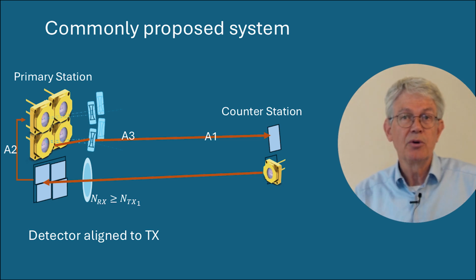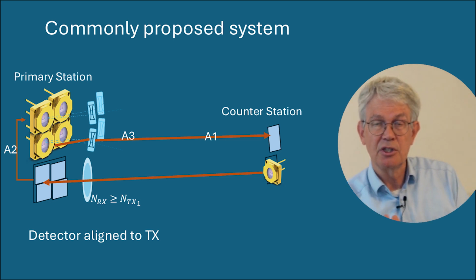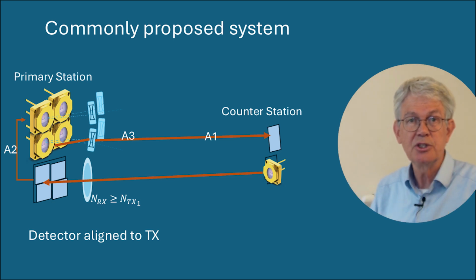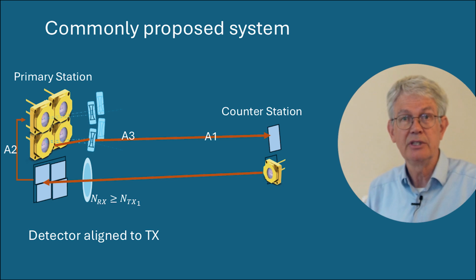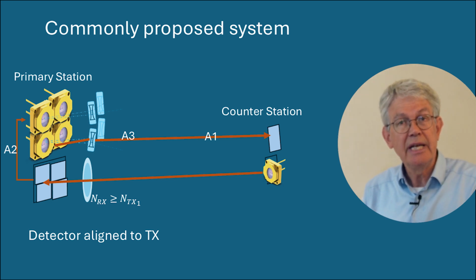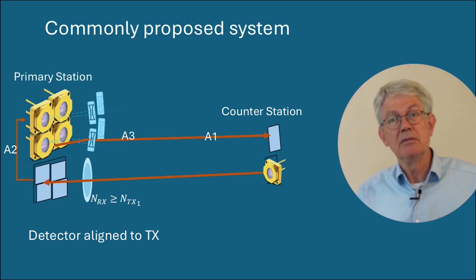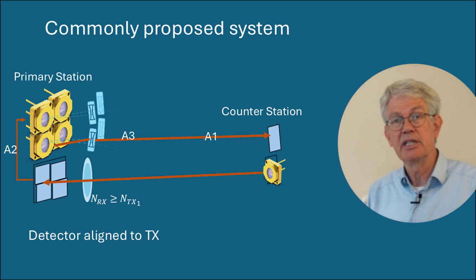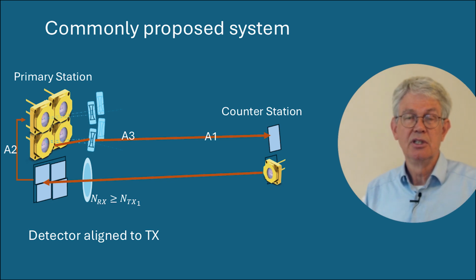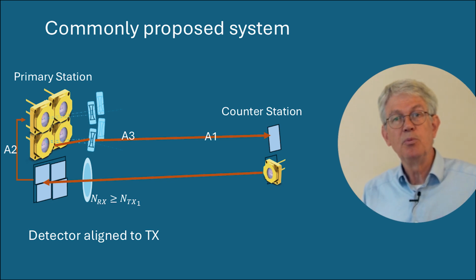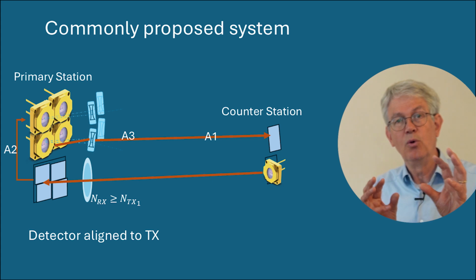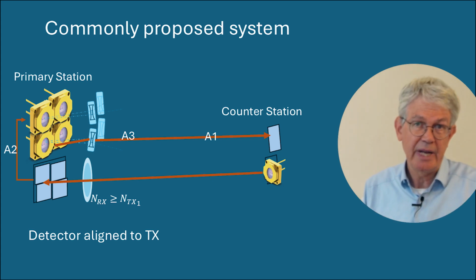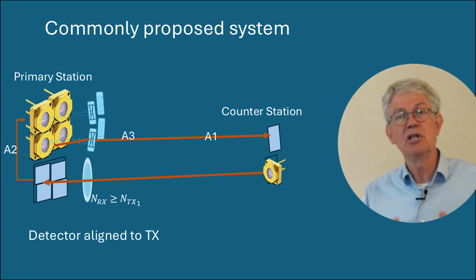So what I've seen before is having a VCSEL array or many emitters, many micro LEDs emitting into different directions, which helps a lot in terms of boosting the signal to noise ratio. You can implement that by measuring the angle towards the counter station by a detector that is also highly sectorized. The question is, do we want that? Do we want to perfectly align the emitter with the receiver? In a production process, that is not a very attractive solution. You would like to decouple that.